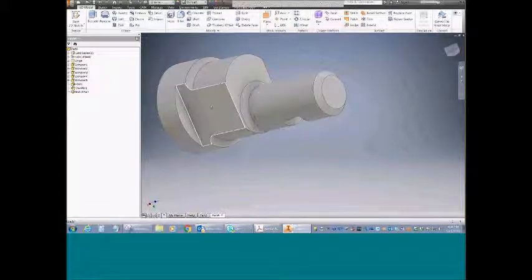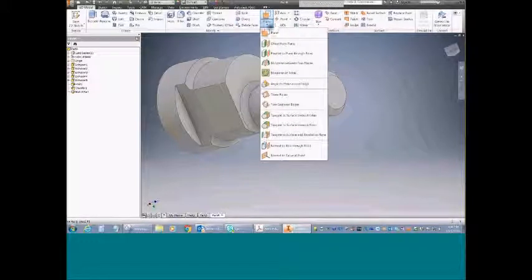The other thing I would show them is that instead of sketching on this flat surface, I would start the subject of planes, and Inventor does a nice job of breaking the planes up into the different possibilities. I know some software lets you just pick on what you want to make a plane, but it's a little hard to communicate to the students what's required for a plane.